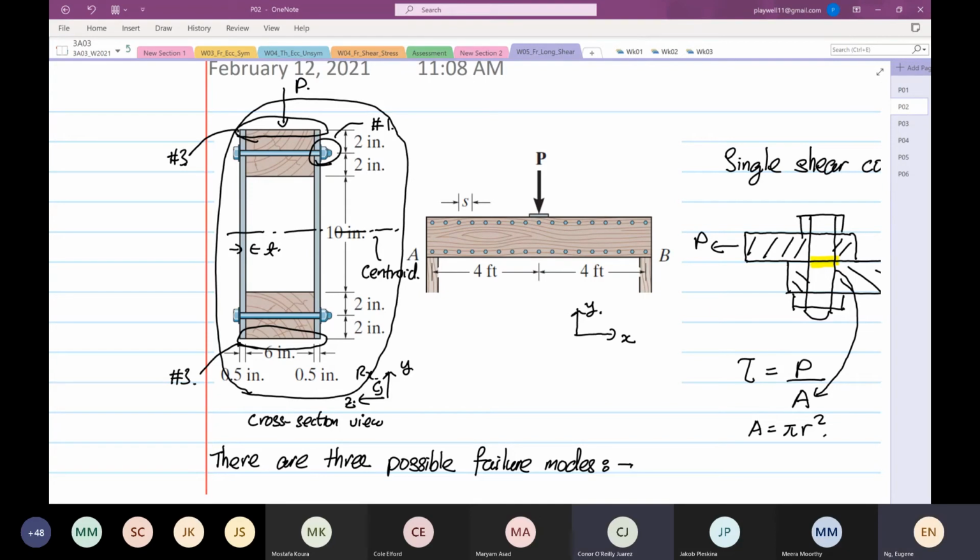Right. So if we're going to draw the normal stress distribution, where is the normal stress highest? At the centroid or furthest away from the centroid? Anyone? Oh, furthest away. There you go. So normal stress will be highest at the most extreme ends, yes or no?